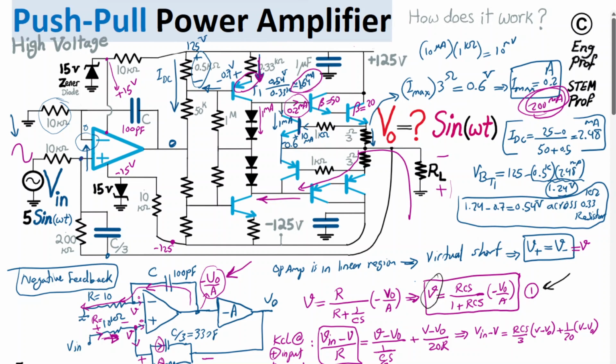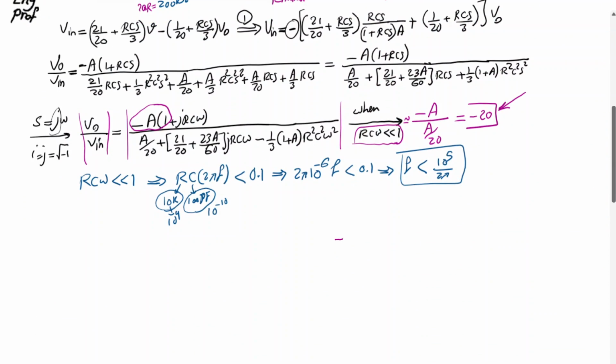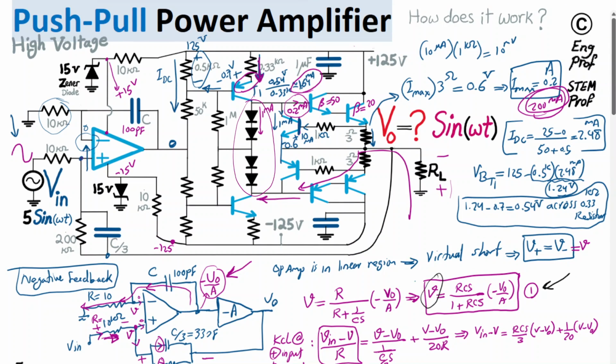What I mean by output voltage dead zones is that in the output, rather than having this sort of situation, and I'm exaggerating, Vout, these are referred to as voltage dead zones. With the proper diodes and biasing, the Darlington transistors are always on the verge of turning on, because these diodes are like 0.7 and 0.7, so effectively they support 1.4 volt, which matches the required VBE drop across the Darlington transistors.